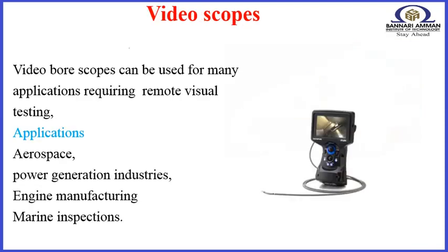Video borescopes can be used for many applications requiring remote visual testing, including the aerospace and power generation industries, engine manufacturing, and marine inspections. Video borescope systems can be used to confirm questionable results of other NDT techniques. For example, an indication can be located with ultrasonic inspection and then visualized with the video borescope.